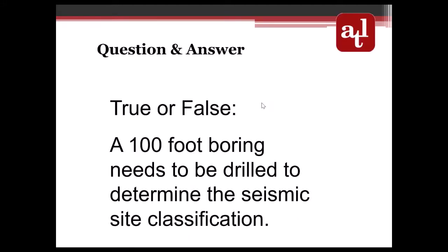So question number 1 was true or false? Does a 100-foot soil boring need to be advanced to determine the seismic classification? And as I stated just a bit ago, that answer is false. We do not need a 100-foot deep boring.